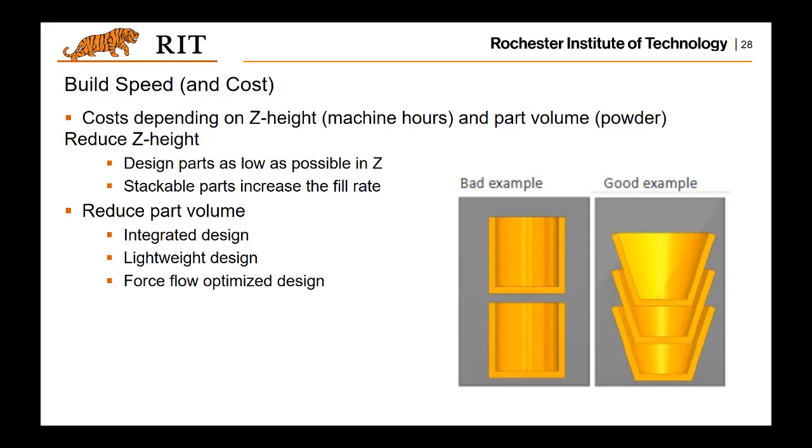So that's why if you have more layers, or if you have larger part volumes, then that will cost more time and material. So when you design your part, try to design it as low as possible in the Z direction.